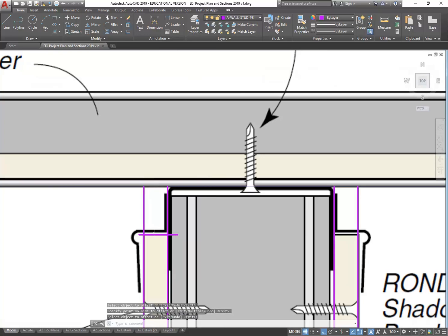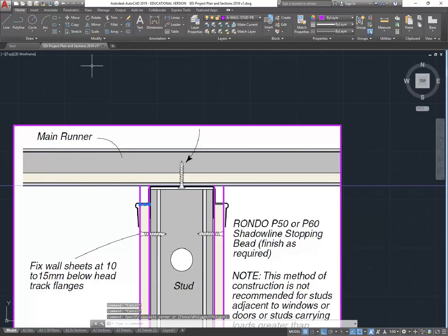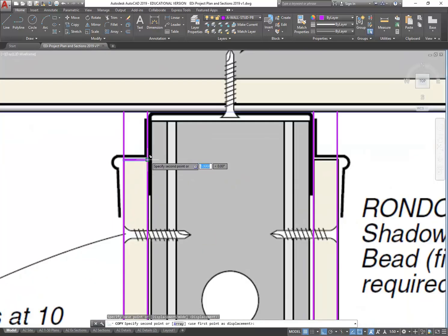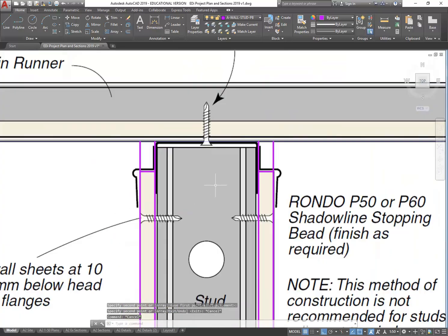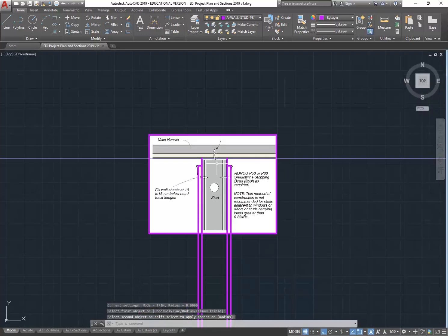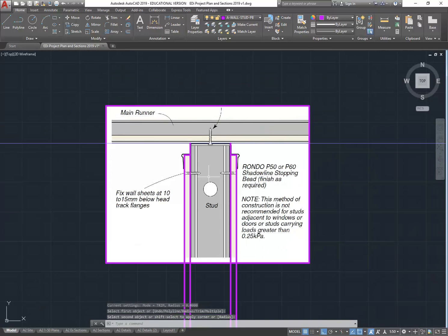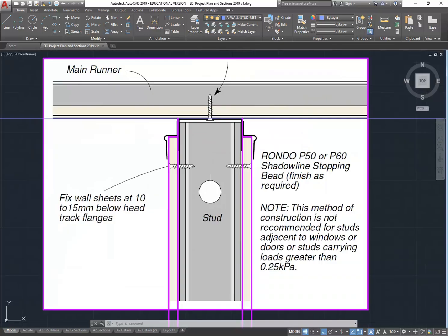and then I can tidy this line up like that and copy it across to the other side, and then fill it. Just make sure it's a 0 radius. Yep, it is. And join these lines together. So very simple, nothing too complicated there. And at most you would then maybe think about putting the circle in, and because I'm fussy, I'll make it centered.